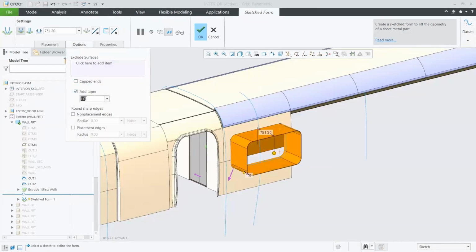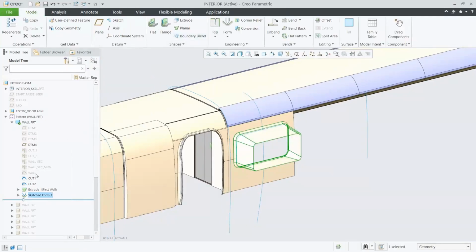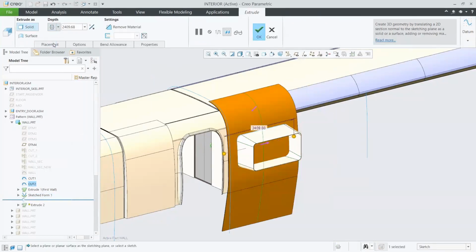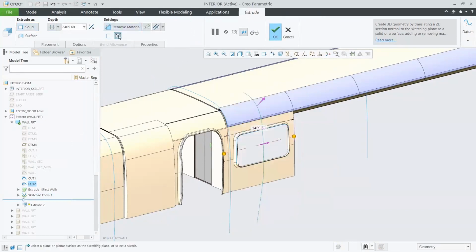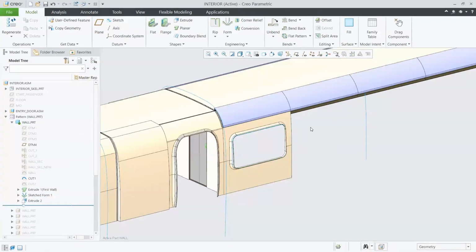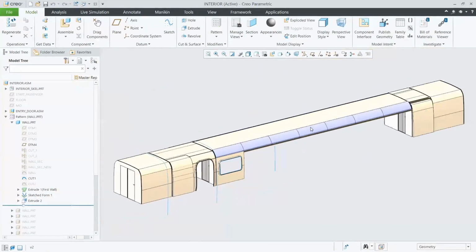Quickly give it a taper here. And in my case, I'm just going to put out a little bit further because I know I'm going to trim it based off of another curve that I pulled in from that published geometry. So go ahead and give it a bit extra here. And then we can use that curve here to trim off what we need. So that outside curve is really controlling how far out this can go and making sure that it's not going to bump into any walls or anything of that nature. All right, so that's looking pretty good.